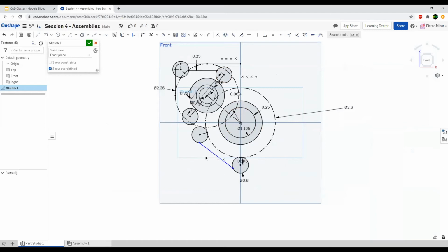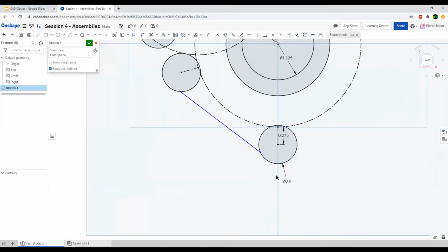But then probably the most confusing spacing I have is these circles. These numbers probably look pretty random. That's because I'm cheating a little bit. On the sketch I made last night that I'm using as a reference, instead of using the whole tool, I just used a diameter of 0.196 for each bolt. I'm pretty sure that's what a number 10 bolt is, so I'll just go with that. And then from there, I think it was 3/16 of an inch around each bolt. And I said, okay, that's good.